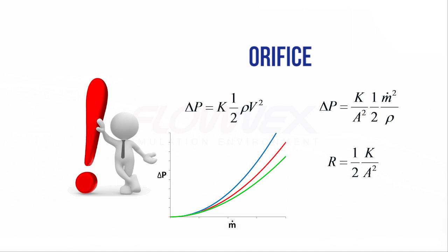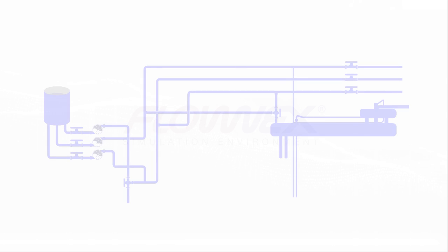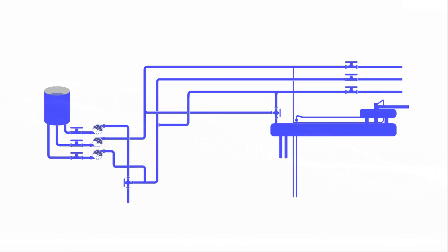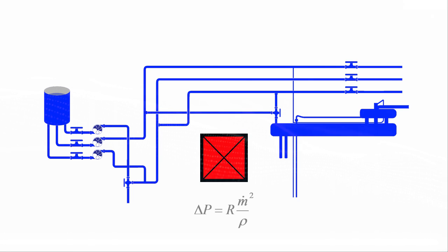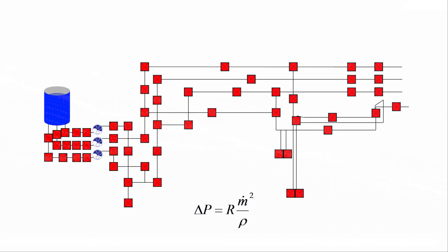Now, why am I telling you all this? For simulation purposes, we can actually model any component that conveys your fluid, except for pumps and compressors, with a single component with some kind of adjustable pressure flow correlation input. So we can then model pipes, valves, sudden expansions, you name it, with just this one tool in our software. Are you following me?